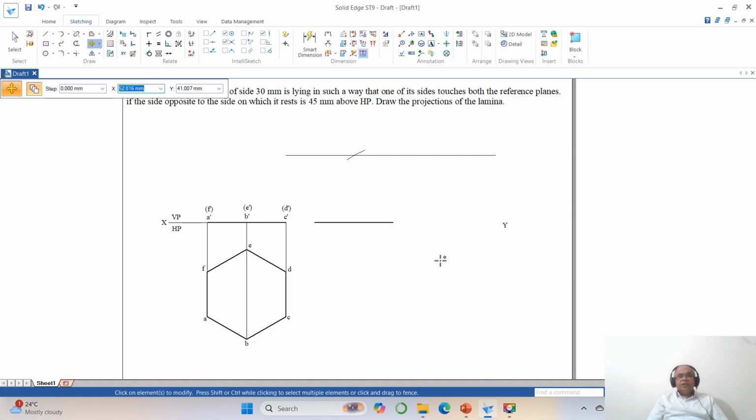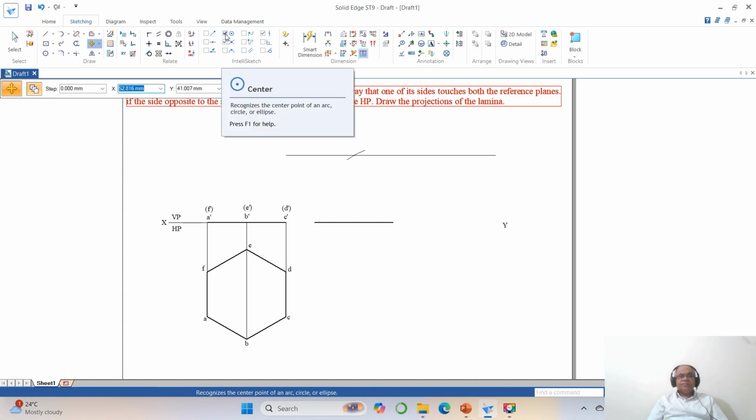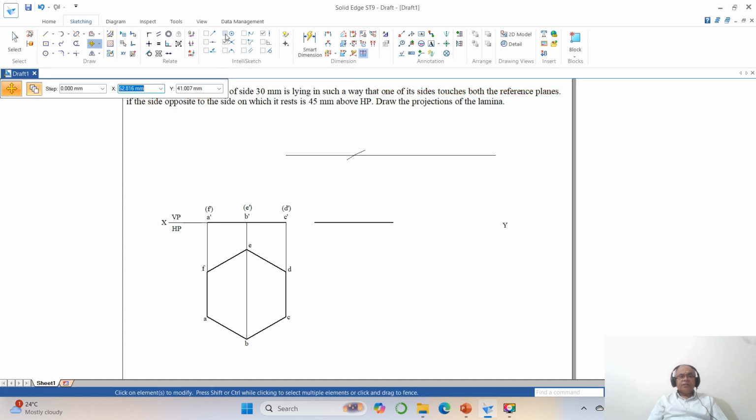Now just enter. Now I want to keep this here itself, and I want to keep this line on this arc. So to do that, I will remove center point and click on the end point. So I will go for the rotate option, take rotate. So disable copy, you select this, take end point of this and click to rotate from end point of this to the intersection point of this.